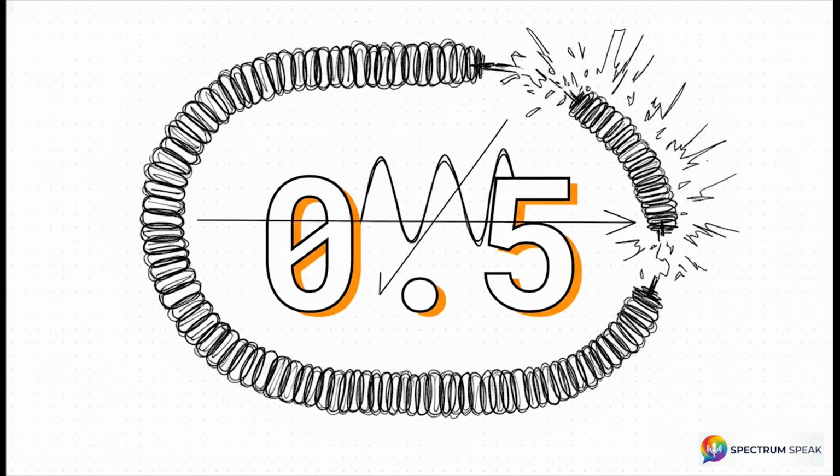0.5 amps. Just really think about that magnitude for a second. A full half amp of current is now circulating your internal signal core, exactly like a transformer coil. And this is entirely due to the sine of that pitch angle geometrically splitting the current. This mathematical reality perfectly explains why spiral shields fail so completely, becoming a huge inductive liability at higher frequencies.